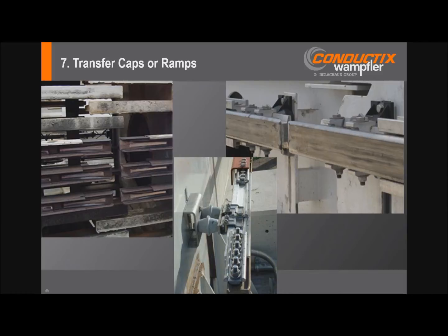One of the things about this is that when the collector is moving across this, it's making and breaking, or breaking and remaking, contact with the conductor bars. When this happens, you get some sparking, arcing. That arcing creates electrical erosion. So these typically are the areas of highest wear, and that's wear due to electrical erosion.